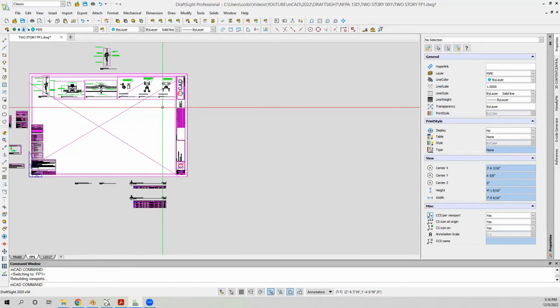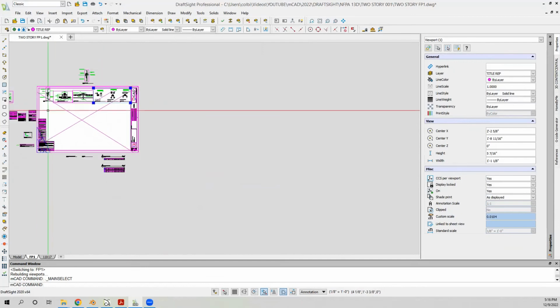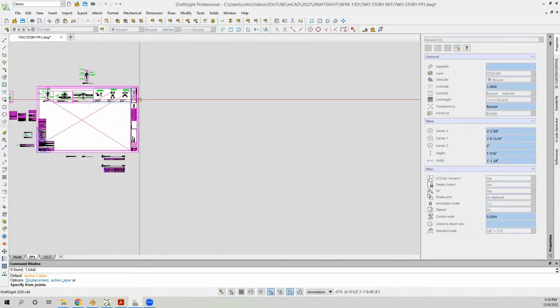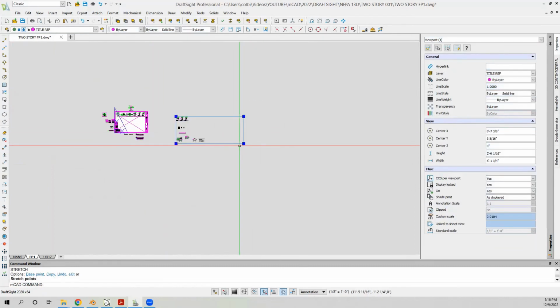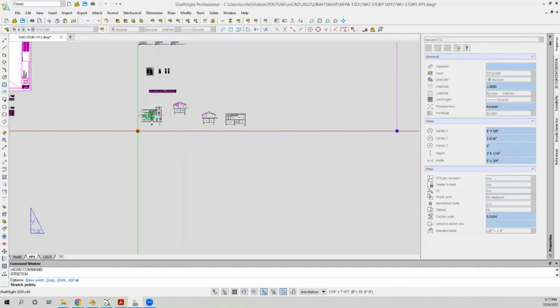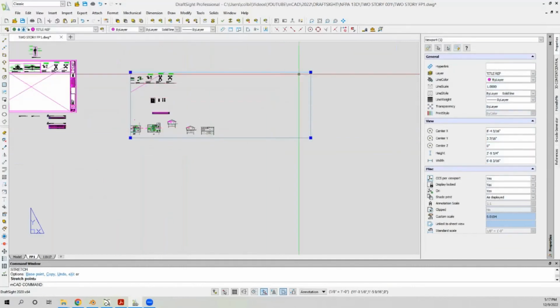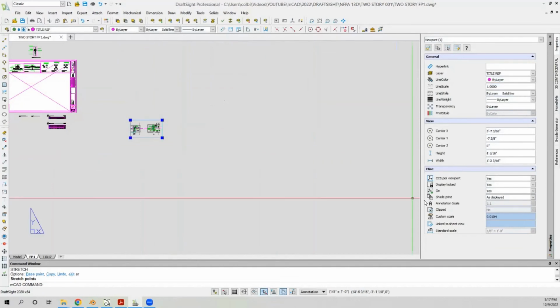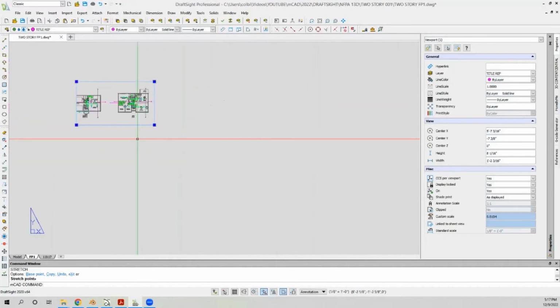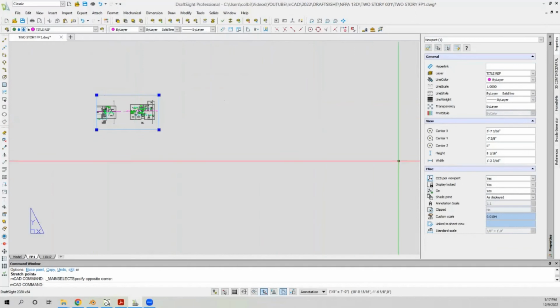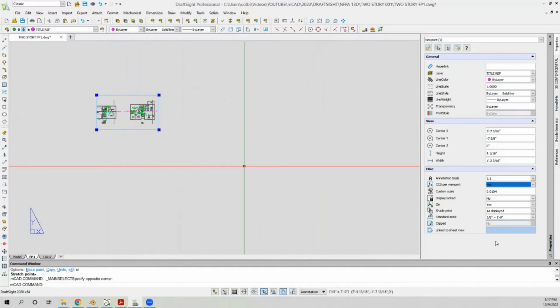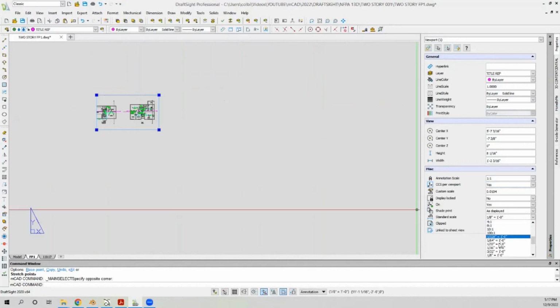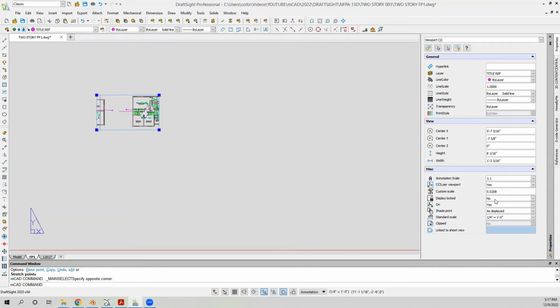Let's go ahead and put our drawing on here, our 2 floors. So I'm gonna copy this viewport so I can use it. There we go. This I believe is set to 1/8 inch scale. So I want to have the plans at 1/4 inch scale. Looks like I got this locked so it won't accidentally get changed. And go ahead and change it to 1/4. And then I'm gonna lock it back up.